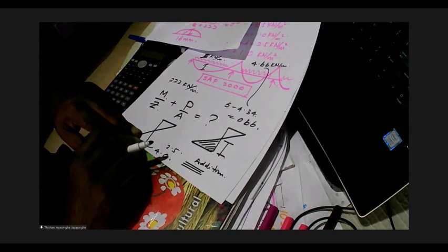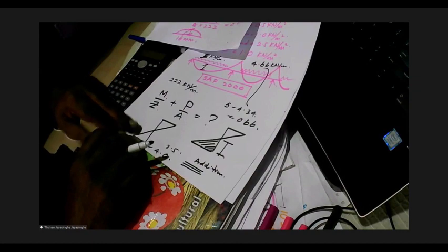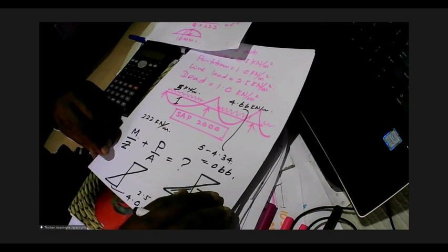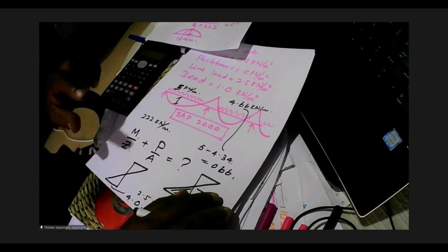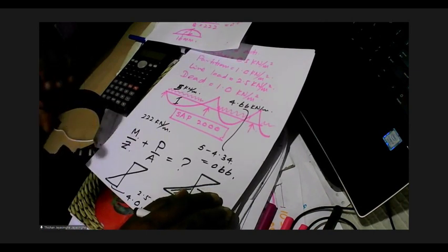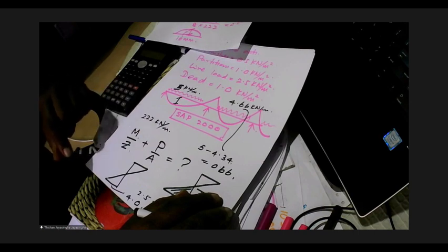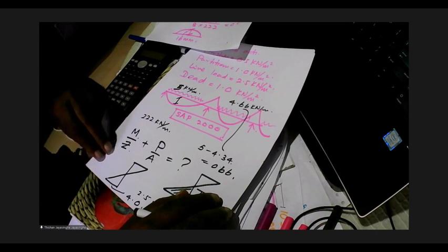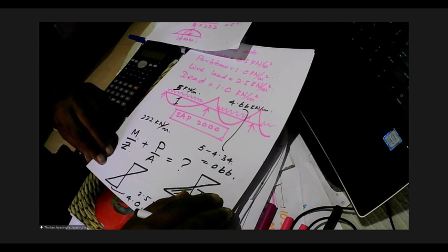So that's what we generally do, because when you do a flat slab design, sometimes what happens is when you compensate the dead weight and provide pre-stress, that pre-stress cannot suppress all the stresses due to live loads.